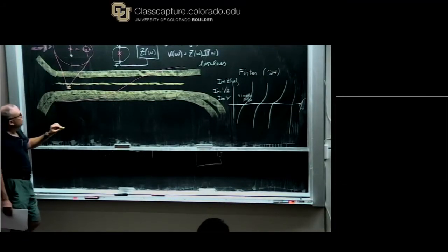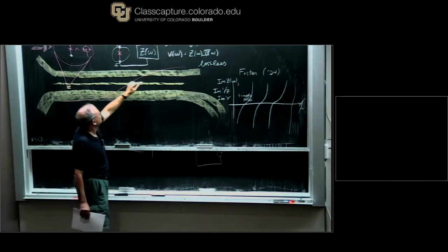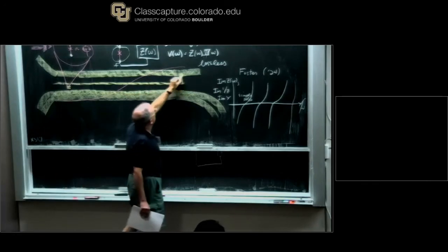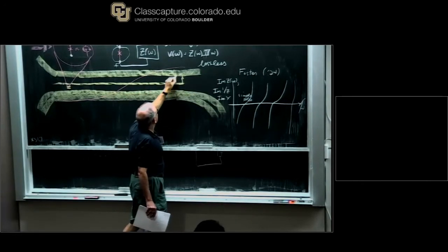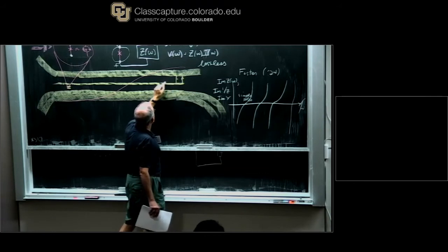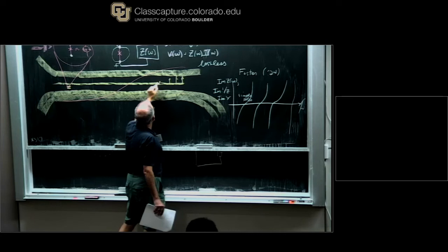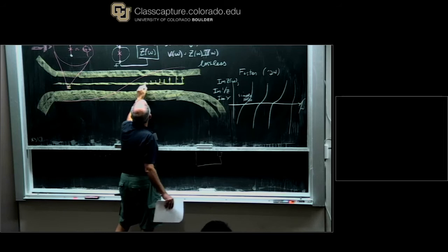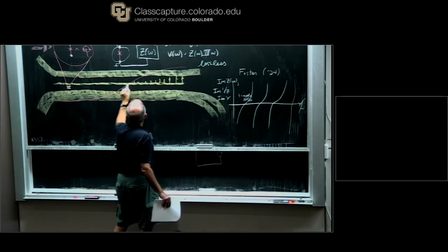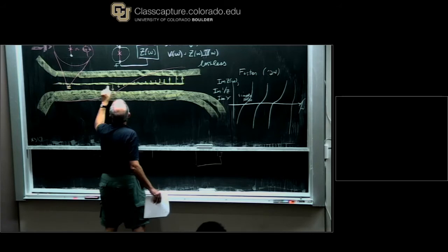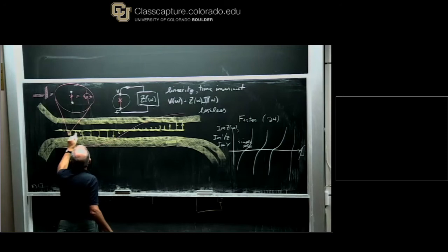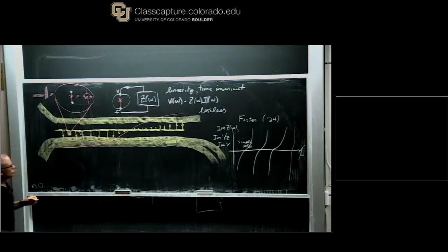And you make your choice based on, I sketched one field pattern, and what I mean by field pattern is the pattern of electric fields. I drew the pink line, which would be, say, the strength of the transverse electric field in this particular mode. But it happens to be a mode in which I fit one full wavelength into this structure, and I'm respecting a boundary condition which is a no current boundary condition.